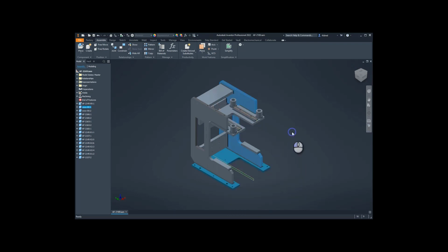Now that can be quite tedious, especially if you've got sub-assemblies and the component that you want to replace is sitting in a sub-assembly, because that replace in Inventor only really works when you're replacing on the same level. So it's the same assembly, or the same level as the sub-assembly. So what we can do is actually go into Vault and replace it, and you'll notice how it will replace it and not actually mess up your model when you open it up again.